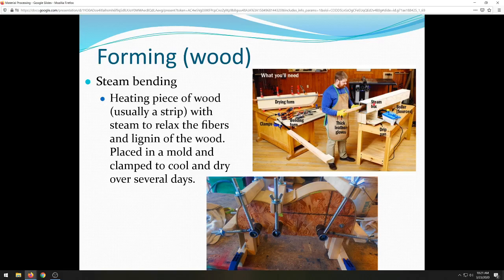He's putting the wooden strip in there. Again, he's wearing thick leather gloves. He should be wearing safety glasses. And then he shuts the door, and that'll sit there. A piece of wood that thick, it looks like it's 1 inch by 2 inches or so. That's going to take an hour to steam enough, probably, where he can bend it.